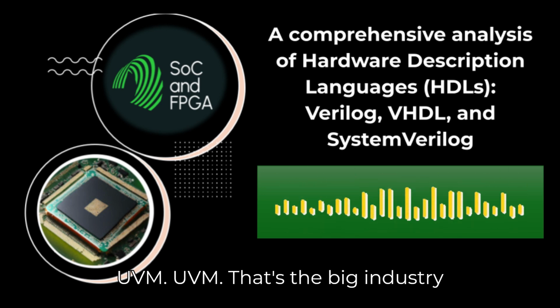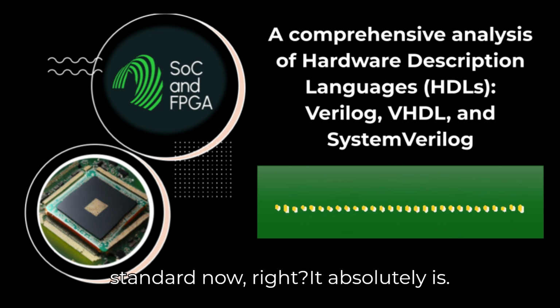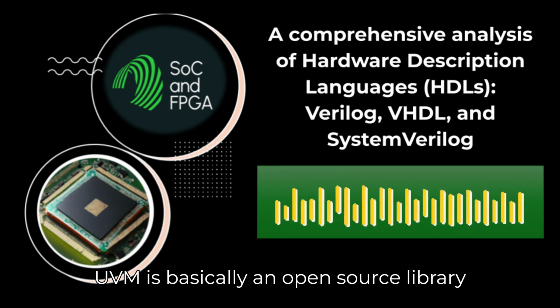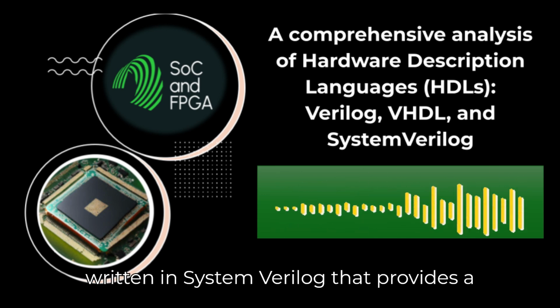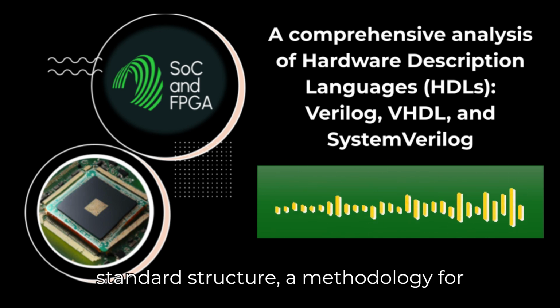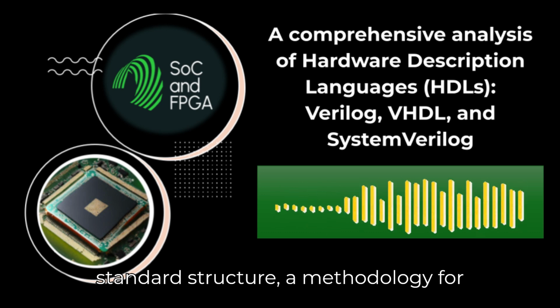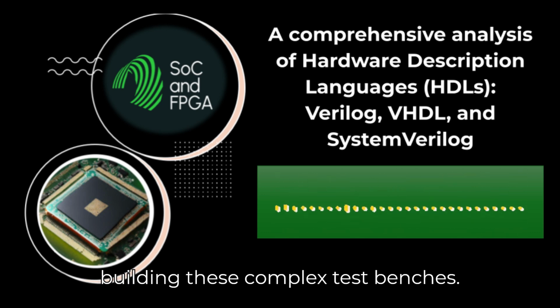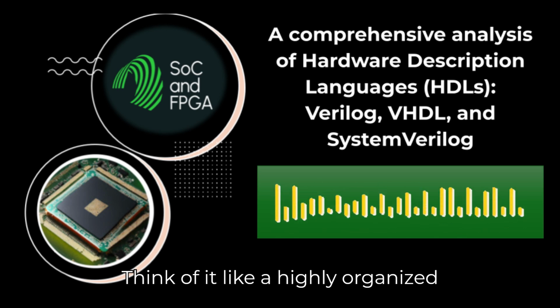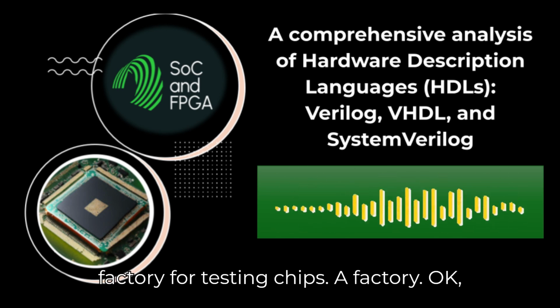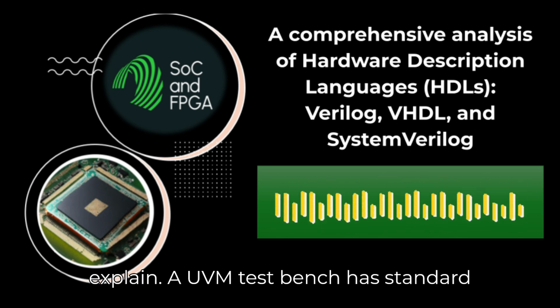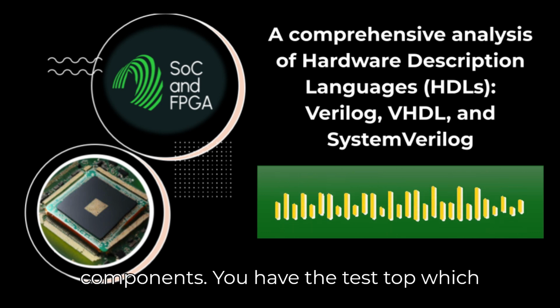UVM, that's the big industry standard now, right? It absolutely is. UVM is basically an open source library written in SystemVerilog that provides a standard structure, a methodology for building these complex test benches. Think of it like a highly organized factory for testing chips. A factory. Okay, explain.